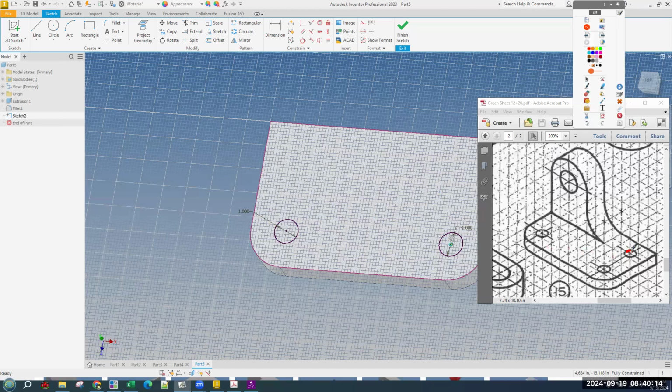All right. So we could finish sketch and cut extrude these, but because this other hole is the same, well, it's the same size circle, but that's not the point. The point is it's still a cut extrusion from the same sketch plane and everything. We might as well do it in the same part feature.